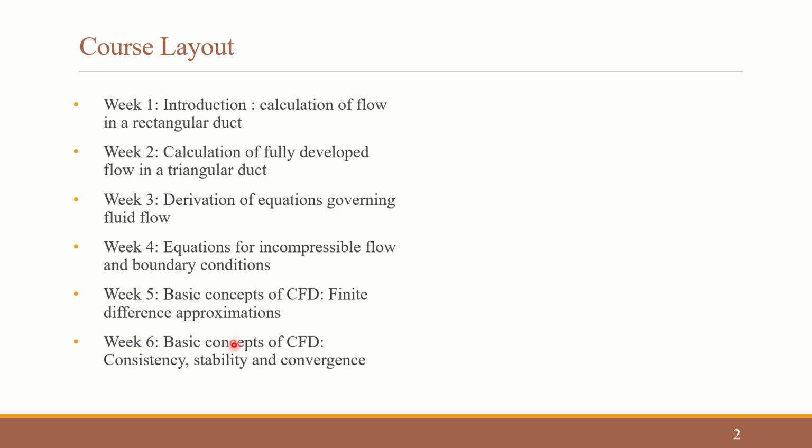And week 5 it is basic concepts of CFD, finite difference approximations, wherein we use the Taylor series approximation to get our finite difference methodologies, and we saw the different orders, different schemes, and how each scheme was giving better results, or when to use which. And later on, it doesn't mean that when we have a problem and after we discretize it that we will get the solution. So we need to have few concepts like consistency, stability, and convergence.